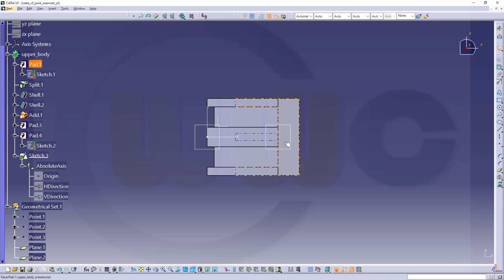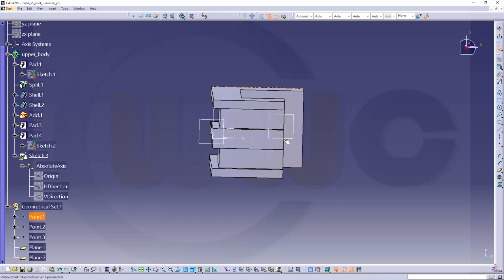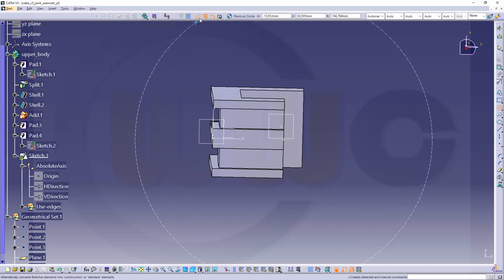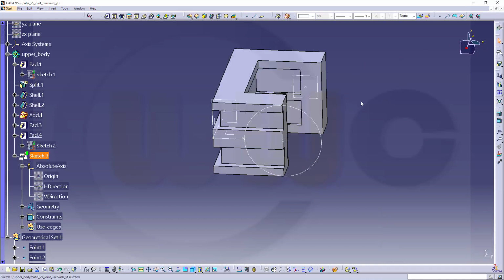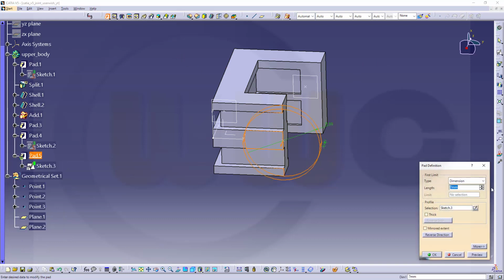And I need that point inside my sketch, this one here. So let's make it for construction and project this point into the sketch. Then put a circle right there. Then you should be able to snap. And this should be not for construction, of course. And the diameter should be 55. Leave that sketch, make another extrude, make it 20,